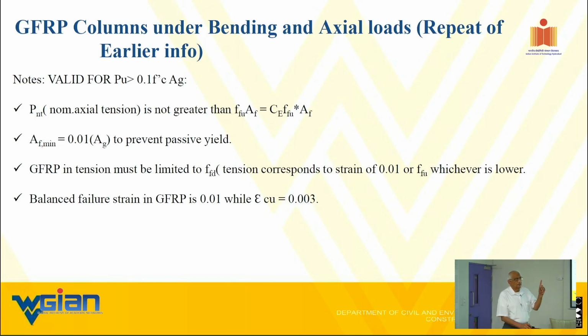Yes. The values are a little bit different. Meaning, as I told you, 0.8 and 0.85. That's also coming from the steel code, except that variation is attributed to the confinement effect. So if you remember, have you done a concrete design course? If you remember, the tie spacing should be less than 3/4 of the minimum dimension.